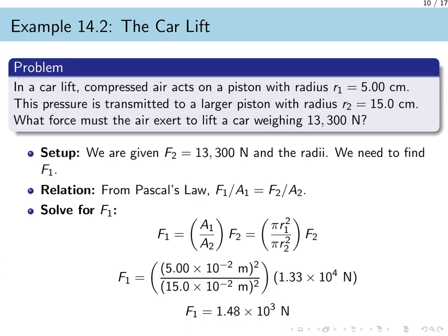Let us apply Pascal's law to a common real-world device, the hydraulic car lift. This example shows how we can use fluid pressure to multiply force. The problem asks for the input force, F1, on the small piston required to lift a car weighing 13,300 newtons.